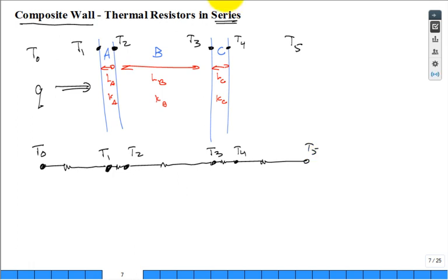And then what we have is we have the flow of heat Q through it. And so if I have 5 watts through that first resistor, it's 5 watts through the second, all the way through, and 5 watts getting dumped out at T5. And then we have our resistance. Now this is a convection resistance. That's a 1 over hA. And that h is on this side. Let's call this the outside. And so that'd be h on the outside. Over here I have 1 over hA. It's a convective resistance. Maybe this is convection on the inside. So I'll put an h_i, subscript i for inside.